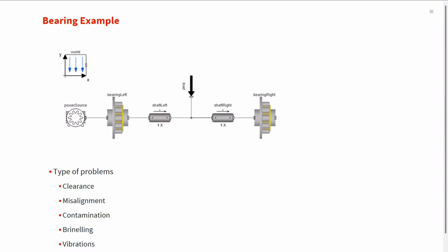And of course, we have vibrations, which are often tied to this defect, signifying deeper issues and amplifying the risk, particularly if machinery speed approaches the critical speed, like whirling frequencies. And we have excessive loads, which challenge us to check the stresses on the roller to discern if an overloading force has been applied and pick a bearing size for optimal performance.